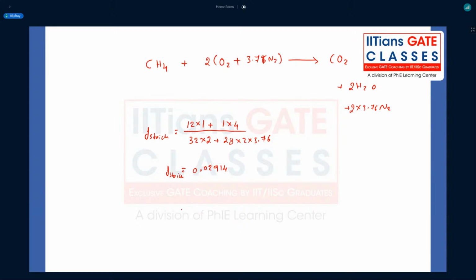So now I can calculate mass flow rate of the methane, that is fuel, is F stoichiometry into equivalence ratio times mass flow rate of the air, right? So you just use all the numbers you have now, 2914 into 0.5. Sorry. F stoichiometry is coming out to be 0.05583.